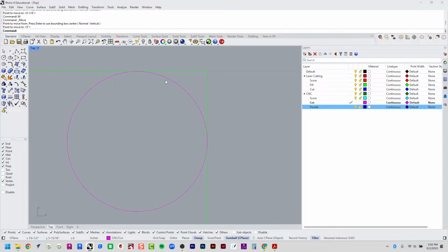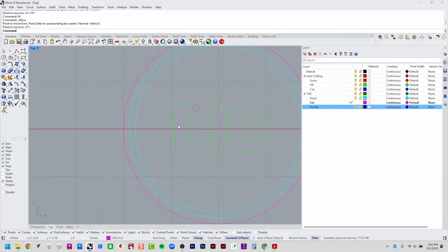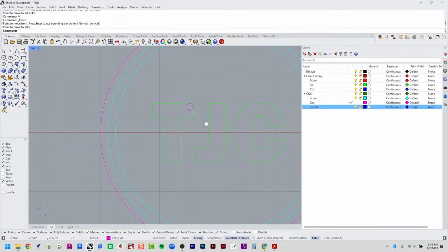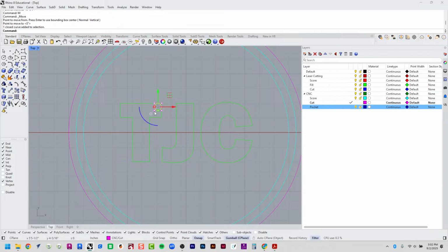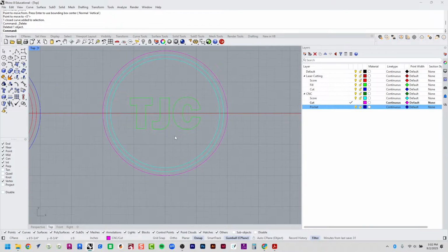It's always going to have a rounded inside corner, but that's okay, at least for the standards of this coaster assignment. The biggest thing I want you to get from this little exercise is that you have an 1/8 inch diameter bit. That's its actual diameter in real life. Just because I can model text that's skinny doesn't mean I can go and CNC skinny text. There are real repercussions. So that's that.